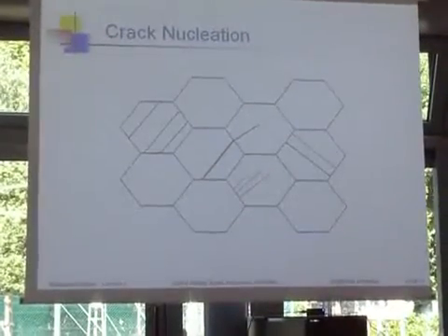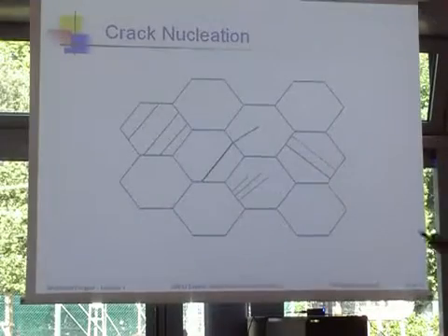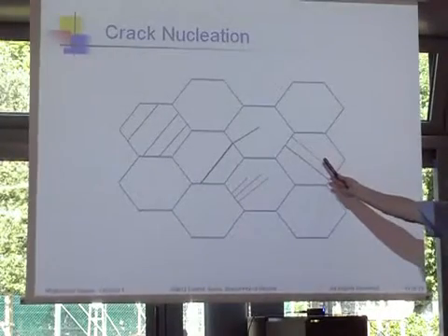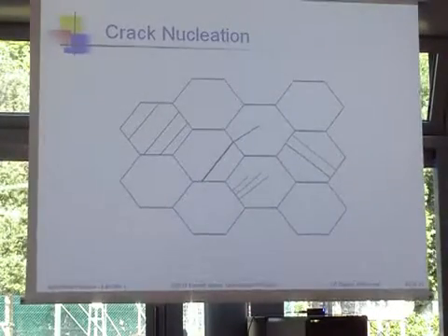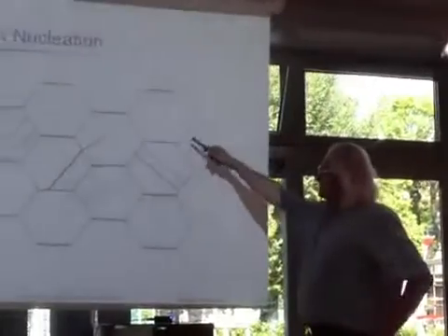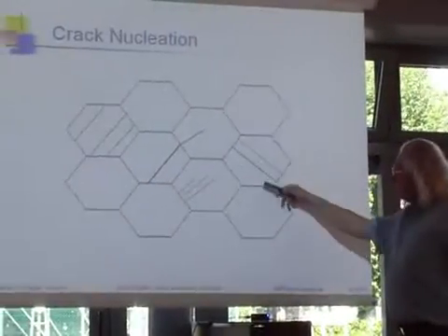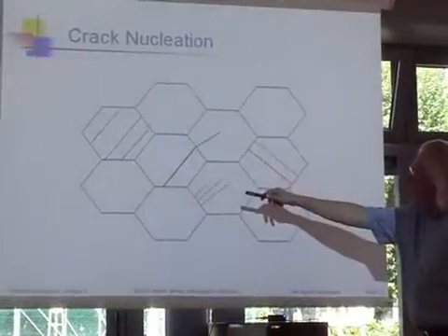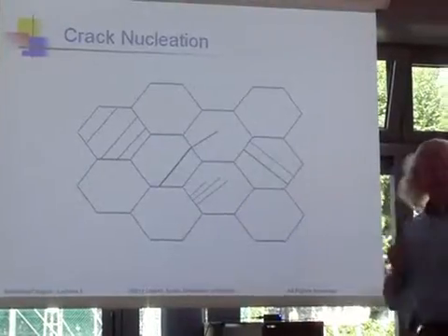And so I drew deliberately, I put all of these at some angle because the process is driven by shear, not tension. Shear, not tension. All plastic deformation is driven by shear. And what you notice is some of the crystals have these shear bands, which will eventually become cracks, and some do not.